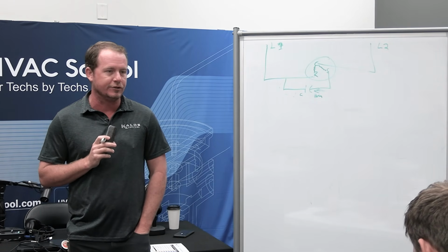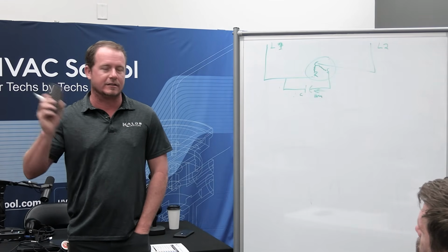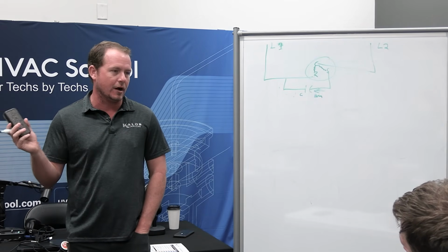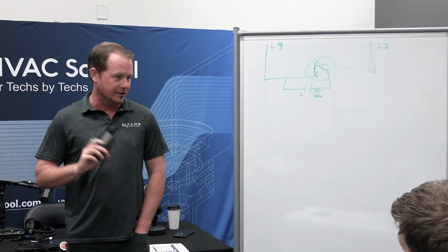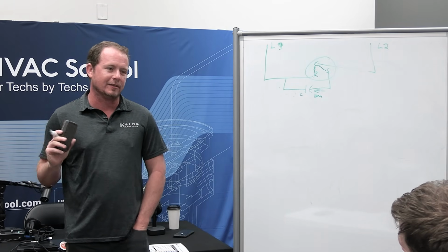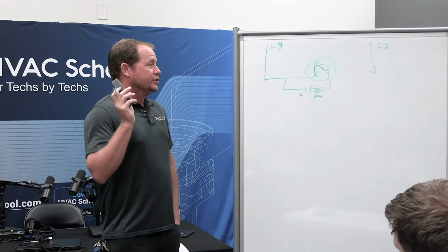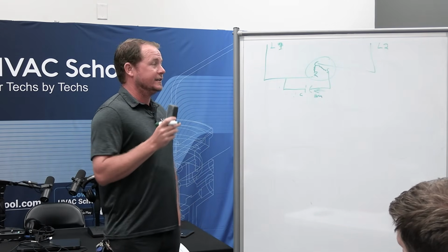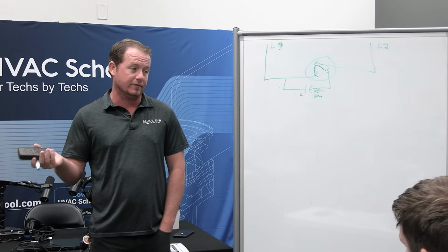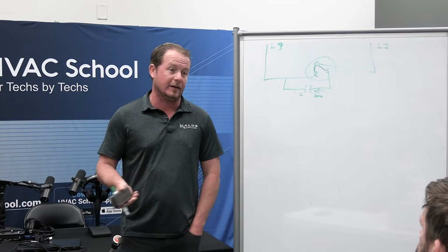And that's why I have no issue using hard start kits for that case. Or even in cases where we have some customers in 208 voltage with really long electrical circuits that have high voltage drop. As long as we've established that it's working well, I'm okay with it in some cases, especially where the factory doesn't really specify an accessory hard start kit. But generally speaking, hard start kits we should install factory ones and only as needed, only when the situation requires it. And in some cases like long line sets, the factory will specify it and say that this should have a factory hard start kit in it.